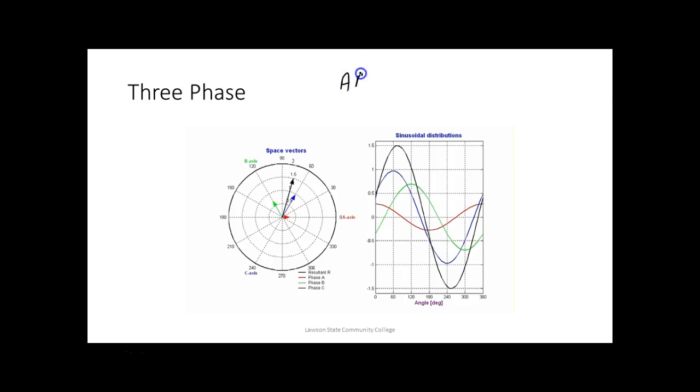So let's say we start off with ABC, ABC, ABC. You understand what I'm doing? ABC, ABC, ABC. Now, what we can do is we swap any two leads. So let's swap C and A. So I'd start off C, B, A, C, B, A, C, B, A.